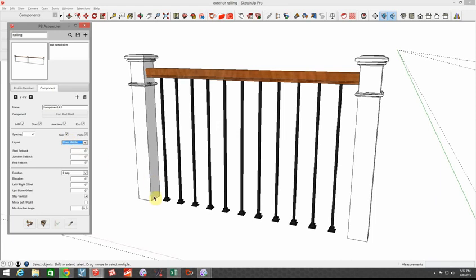But what I don't want is for there to be a baluster and boot right in the beginning or inside these columns. These are 4-inch box newels, and I've got no more than a 4-inch spacing in there. So I'm just going to come in and say for the start, a setback of 6 inches. And I'm also going to do that for the end setback and for the junction setback as I turn a corner. Again, we don't want balusters that are going to be hidden by these newel posts. So when I place those in there, you're seeing all those shoes dotted across in here.